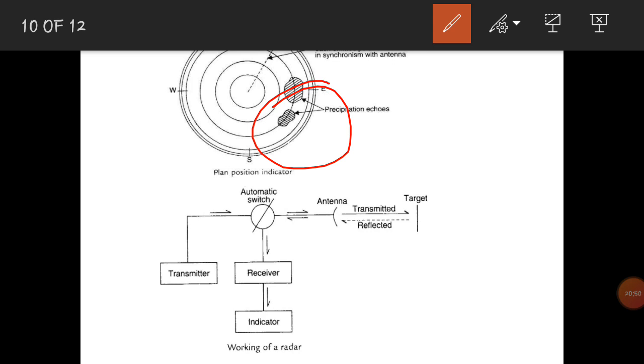One source of reflectivity measurement error arises from hardware calibration. Frequently, even after careful electronic system calibration, large unexplainable systematic error in rainfall measurement remains. Desirably, that calibration should include an independent source, that is comparison with a rain gauge or disdrometer.